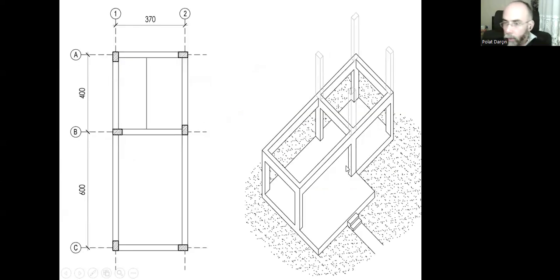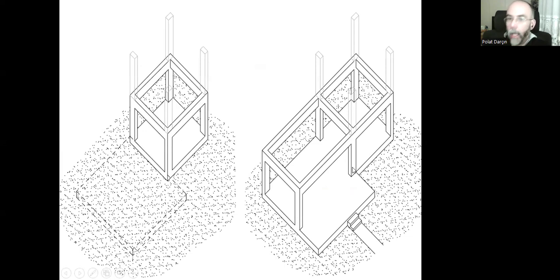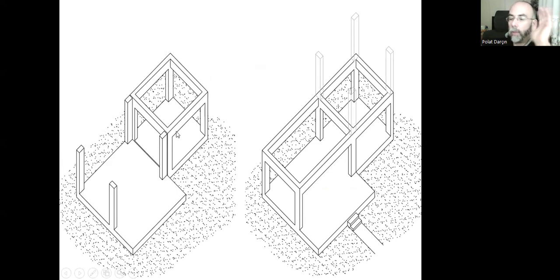So instead of designing the structure like that, first we do the seismic gap, dilatation in Turkish. First we construct this part. We have 4 columns connected with 4 beams, and we do the upper floor and the lower floor. Once the construction is finished, we leave the gap of 5 centimeters, a total gap without any connections, and after that gap, we start to construct a new building.